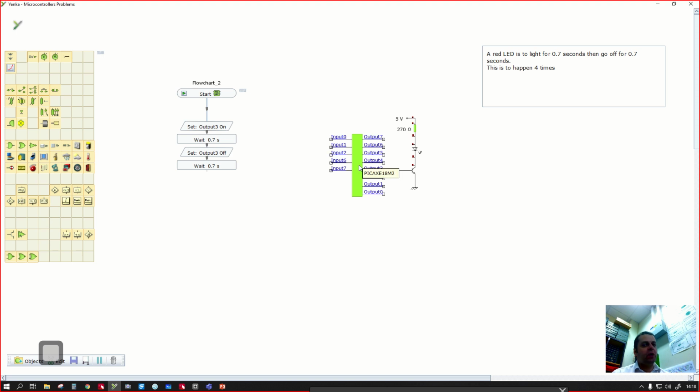Different microcontrollers have different amounts of memory. This microcontroller's got a small amount of memory that we can use. It's got little boxes that we can store numbers in, and the boxes have names. The boxes are named B0, B1, B2, B3, B4. As long as we use those names, we can ask the microcontroller to remember things for us in there. We can only ask it to remember numbers, right?